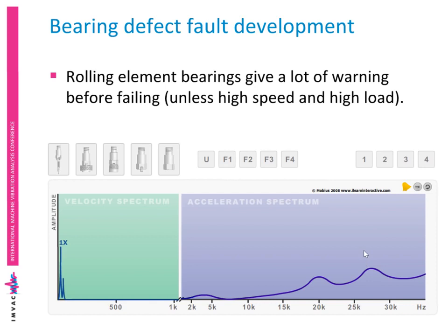So in the very early stages, we're seeing very high frequency vibration. So the enveloping techniques and the peak views and shock pulses and so on detect that. But notice in the normal spectrum, we're really not seeing very much at all.